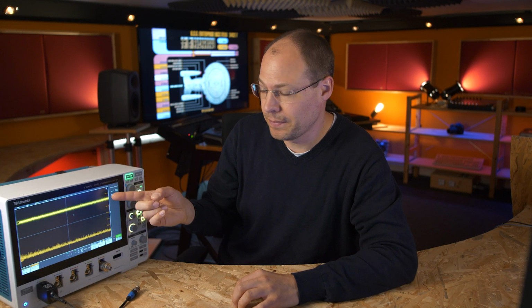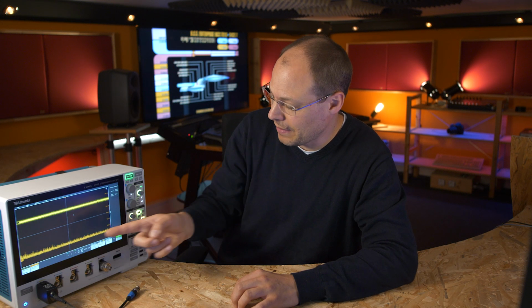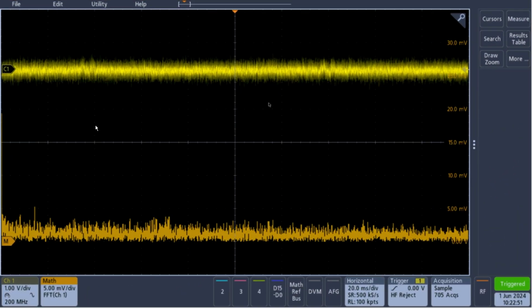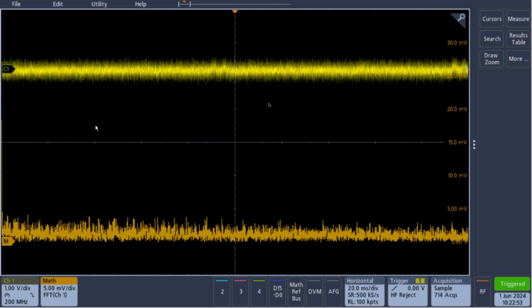In the end, we can check how good our system is in terms of frequency response by looking at the frequency spectrum. In a perfect world, we will only obtain peaks at those frequencies at which we also excite the system. So let's have a look at the signals in the time domain and the frequency domain. The FFT is configured that we can see 0 kHz up to 25 kHz. And let's start at 50 Hz.